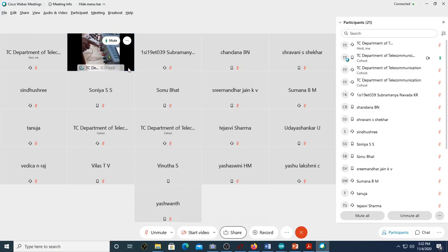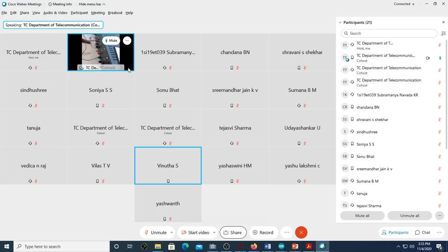You can see here, we are using one power supply. This power supply is used for VCC2. Can you see this is 12 volt? And the other one, VCC1, that is required, we got it from your Arduino side. Can you see pin number 16? Pin number 16 is going to this orange, and this orange is ultimately going to the power supply of 5 volts.